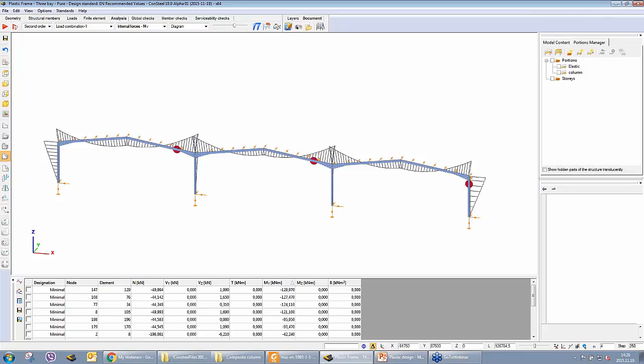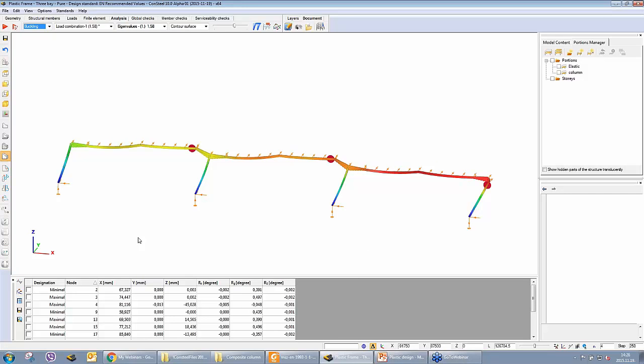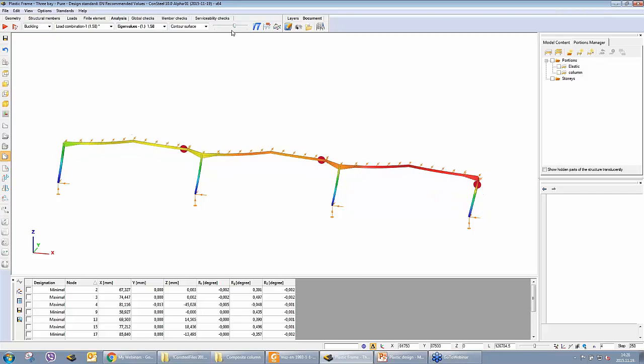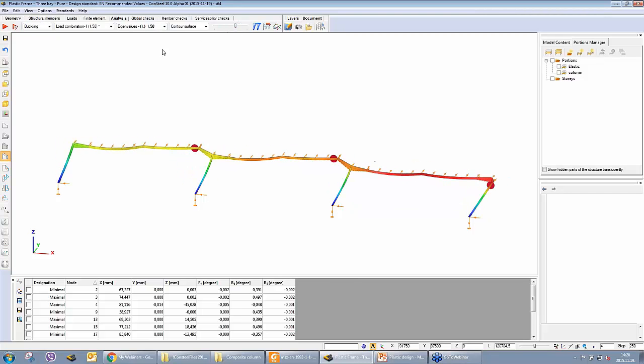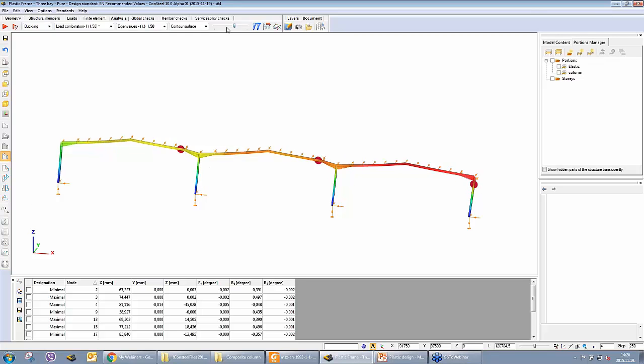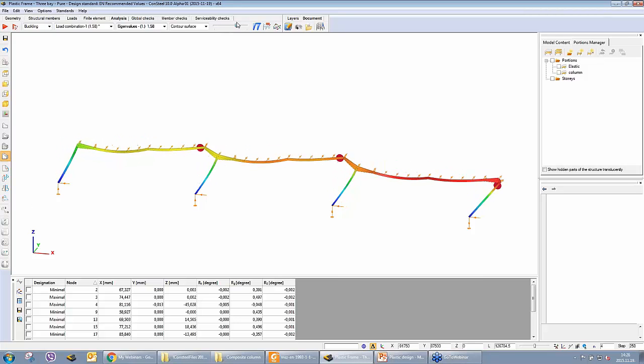So I wanted to stress this and the possibility in ConSteel to treat this. And not only calculating the second order, it is very important that we always can see the buckling results, so visually and quantitatively can calculate what is the critical value, what is the relevant buckling form if we use a second order plastic hinge analysis.